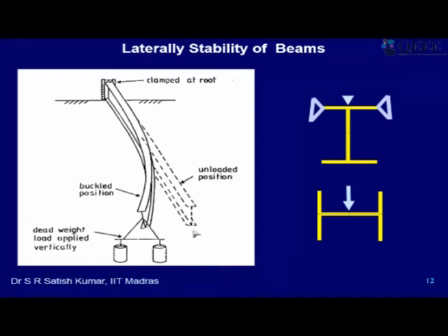So you have to now understand that even the normal plastic analysis will not be valid, or the stress analysis itself is not valid. We have to do a buckling analysis. Just as you took a column, went on putting axial load, your P by A was your stress, and your stress had not reached Fy, but before that it reached F critical, so it buckled. So here also beams can buckle at loads much below their moment capacities for corresponding supported beams, and this is how you have a problem, right?